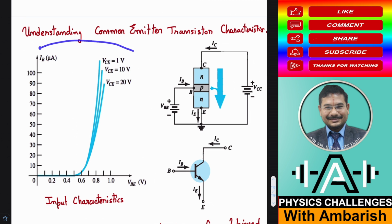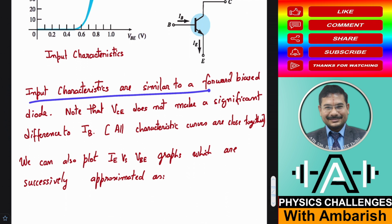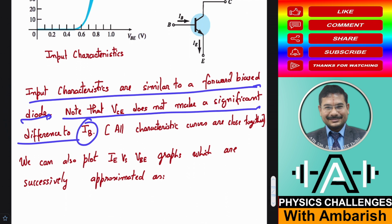So that explains this characteristic curve for the input characteristic, that is this base biasing battery. This should be more than 0.7 volts, that's all. And once it is more than 0.7 volts, the base current varies as shown here. Input characteristics are similar to a forward-biased diode. Note that VCE does not make a significant difference to IB.